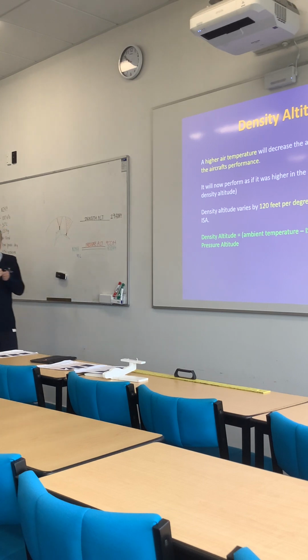Okay. So after taking into account the temperature, we've come up with a density altitude of close to 3,000 feet. The aeroplane's still physically taking off from an elevation of 810 feet, but it is performing as if it's at close to 3,000 feet, where the density is reduced and the takeoff distance would be much higher.